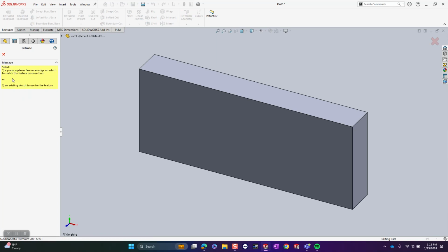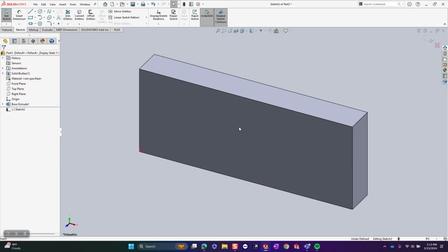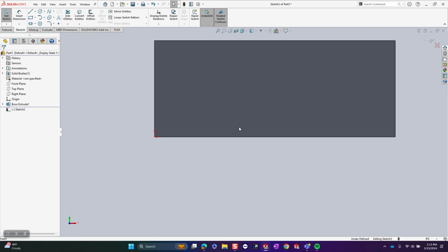Once again, it's telling me where do I want to do my sketching. And the difference between last time and this time is when I started with this initial feature, I chose datum planes. In this case, I'm going to choose the face of the part here. So I'm just going to, right in the middle, just select that. And depending on your screen, it may or may not go flat. I'm going to make sure mine does, so I'm going to do a Control-8, just so that I can look at this in two-dimensional. So yours may have done that. I'm not positive.